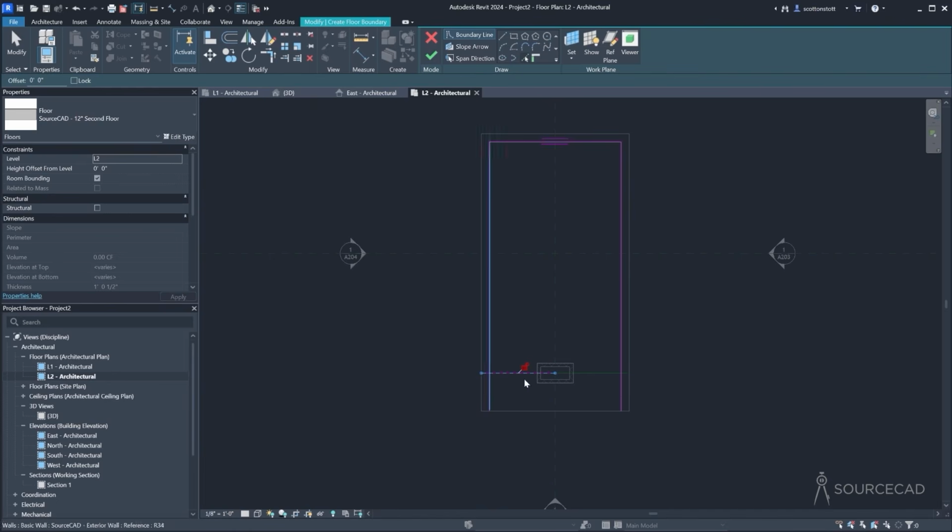We have lines, and typically what we do is we use this tool right here, Trim Extend to Corner. The way that tool works, and the keyboard shortcut is TR for trim, is you click on the two edges, 1, 2, and they're joined in a corner. It's like AutoCAD's Fillet 0 command, if you're familiar with that. You click on two edges and they're joined in a corner. And what you get depends on where you click the lines.